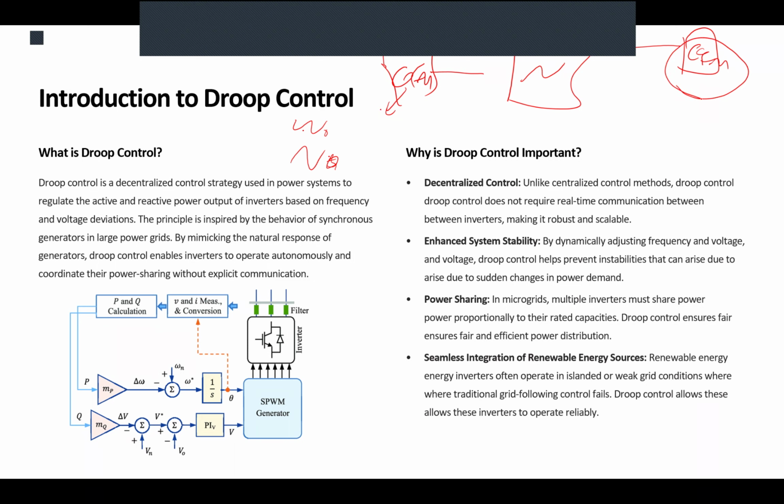Same goes here. Now, in the network, if something happens, like a decrease or increase in the load, which causes a deviation of the voltage or frequency at the terminals of the GFM, the GFM, because it has its rules and regulations, says, okay, I do not tolerate that increase or decrease in frequency and voltage.